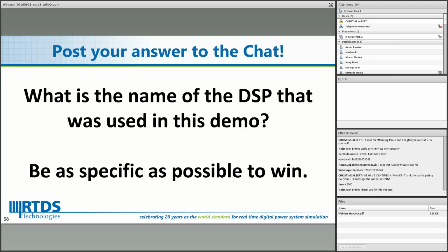Then we had a look at the way of modeling a switch in RTDS. Then we moved over into the next topic in our presentation regarding the interface. We looked at how to interface the circuits inside our simulation, what I called the internal interface. Then we had a look at the external interface, which is regarding the I/O card in RTDS. Then we had a look at all those available models in the RTDS small time step simulation library.